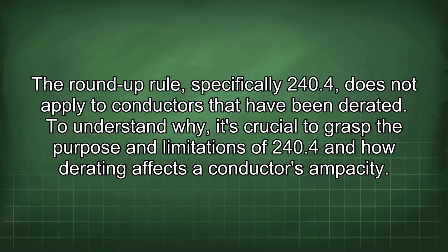The roundup rule, specifically 240.4, does not apply to conductors that have been derated. To understand why, it's crucial to grasp the purpose and limitations of 240.4 and how derating affects a conductor's ampacity.